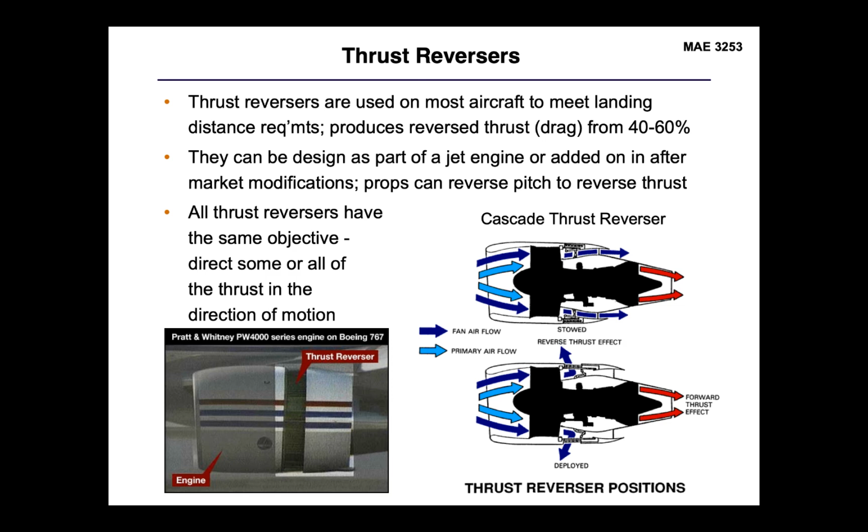First, it dumps that thrust, because you can't just turn the engine directly off. It's still spinning. It requires some time to spool down. So there is going to be a delay between how long it takes for the pilot to input control to the thrust of the engine and how long it takes for that thrust then to change on the engine itself.